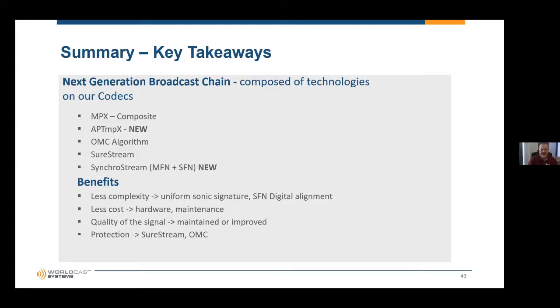Well, there's always going to be some vagaries in the network, but provided you've got good network connectivity, there will be no observable difference between the composite signal that comes out at the other end, because even if it's analog going into the codec, it gets digitized right then and there into the AES 192 sample rate. Once it's digital, it's going to be exactly the same coming out the other end. We just decode that digital signal. As far as levels go, everything should be maintained. Should be identical.